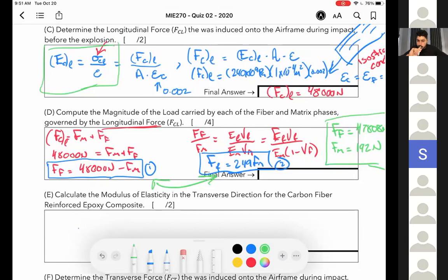In the tutorial video, we did something like F_f divided by F equals 0.9 divided by 0.2 when calculating the ratio for the tutorial question. Why don't we use the same ratio equation here? Because we're not given... Oh, so you're saying that's not a standard ratio. The problem told you that 90% of the load is carried by the fibers. So we created that ratio based off of what was given in the problem. That's not standard. That was for that specific problem.